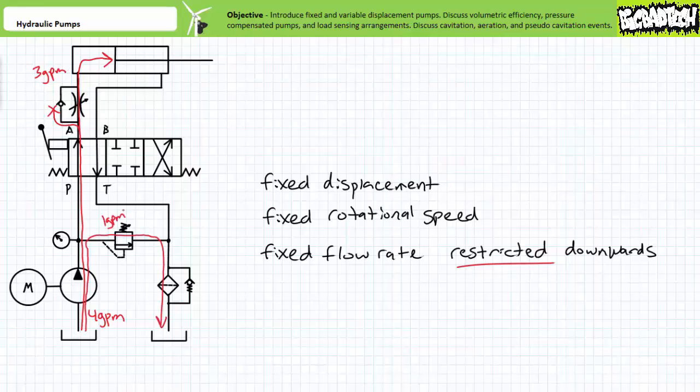This means the excess 1 gallon per minute of flow produced by the pump must be diverted to the tank at maximum pressure by the pressure relief valve. This is to suggest that directly varying output of the pump may be a more efficient option than restriction-style flow control valves. However, this isn't always an option, especially for simple, inexpensive systems. We'll examine flow control valves and flow control methods in greater detail in later lectures. The focus of this lecture is to really just concentrate on general pumping methods.